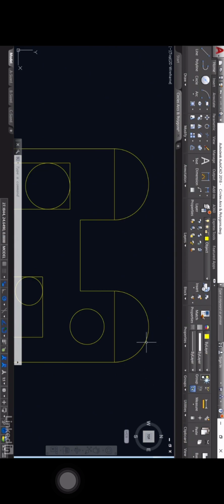Let's delete that arc there. I'll just delete it using the delete key, select and delete. Let's go back to fillet again. So I click on the flyout and select fillet, and I go that line there, places the arc automatically. It's a lot quicker than start, center, end. Now, as long as you've got 2 parallel lines, either vertical or horizontal, you can always join the 2 ends of the line with an arc like that. It's a quick little way of drawing arcs.